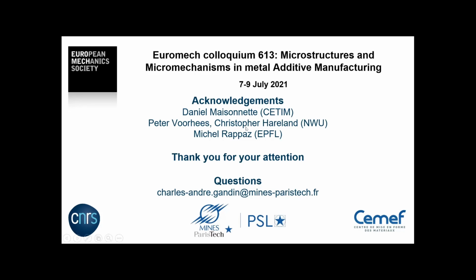No, well, there is a heat source, and we consider the interaction between the heat source and the powder and the liquid, but we do not directly simulate the laser diffusion by ray tracing from one particle to the other, and this is not possible with this methodology.